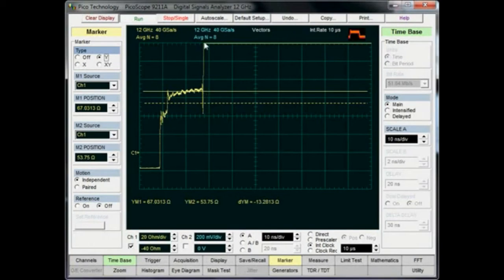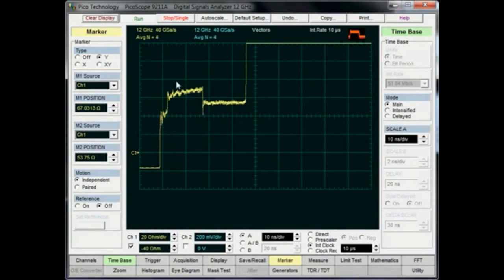This is the output going to a very high impedance, so I'm going to connect, as a second example, a length of 50 ohm cable to the T-piece at this point. So I'll connect my 50 ohm cable, just clear the display, and here we can see now the 75 ohm cable and then some 50 ohm cable, so I could put my second marker on that point and see here that it's indicating this cable has a mean impedance of 55 ohms.